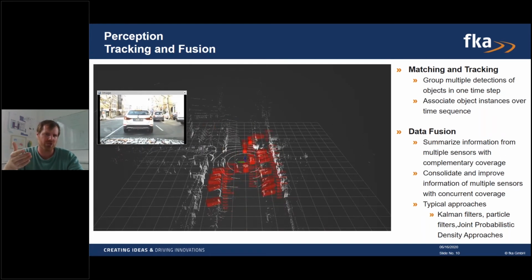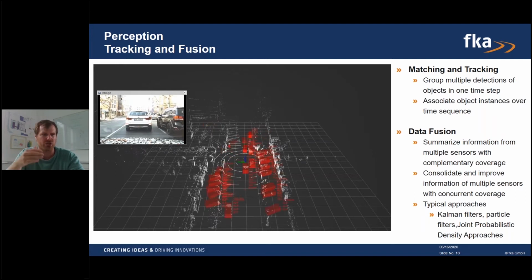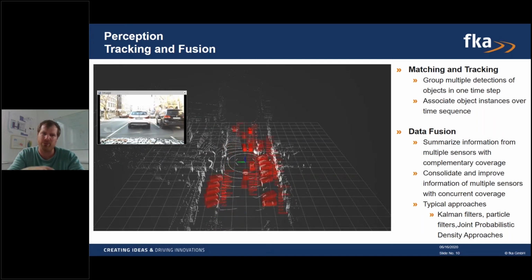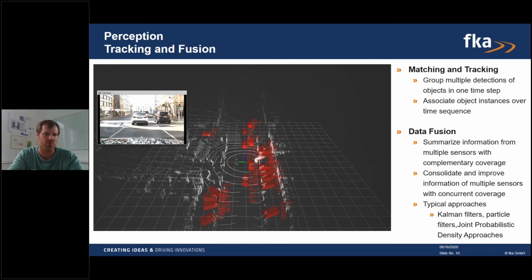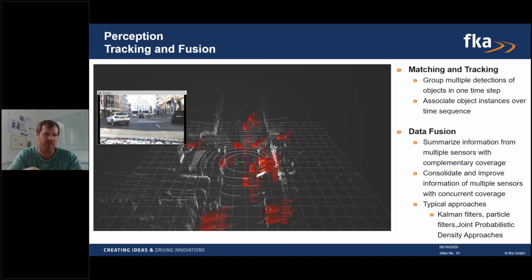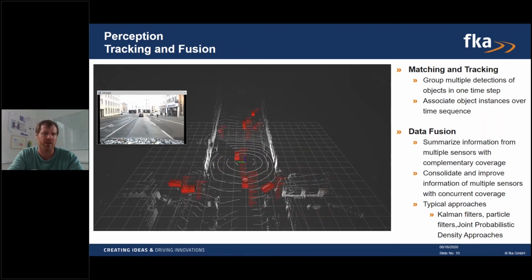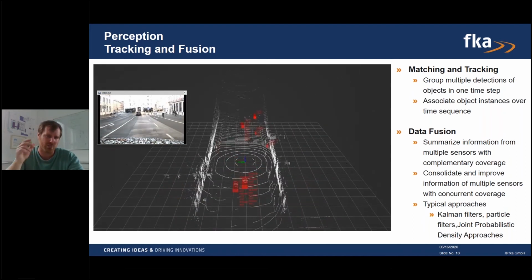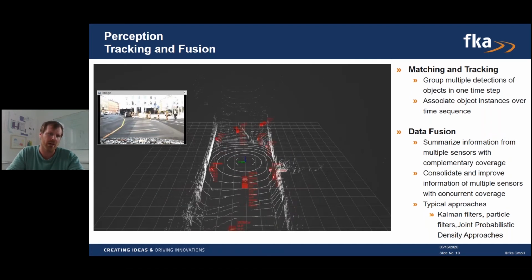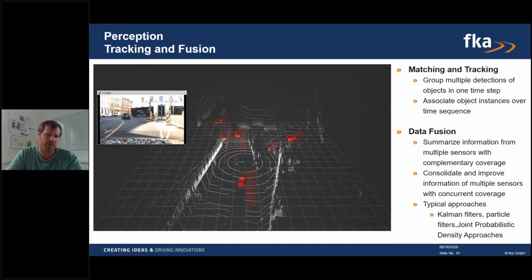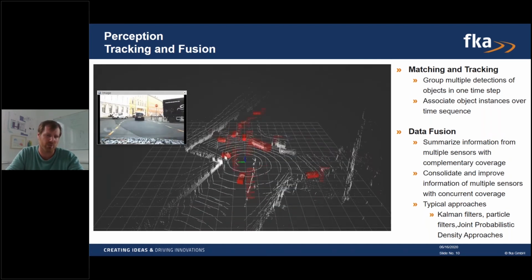For example, we try to track the objects, and if we saw a car in the last frame, then we make sure that it should be there in the next frame. That's the same as what a human would do. He knows we've seen a car there, maybe it's in the blind spot, some sensor can't see it, but it would still be there. So that's where tracking is really important for a stable object surrounding.